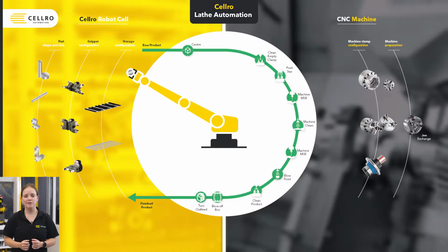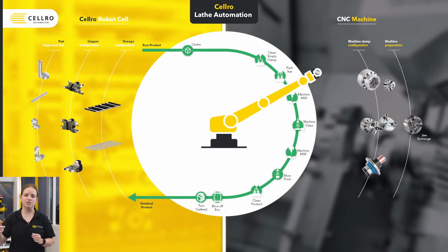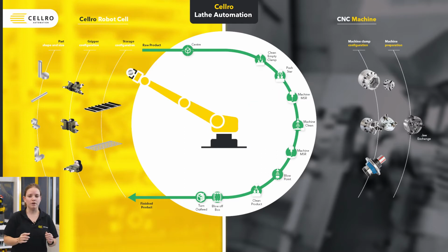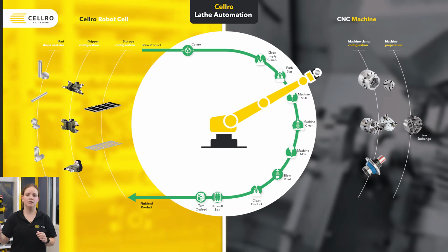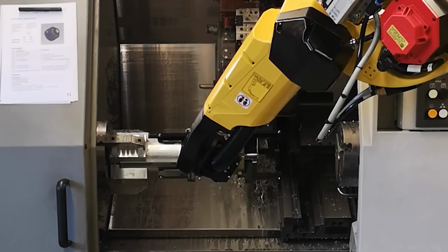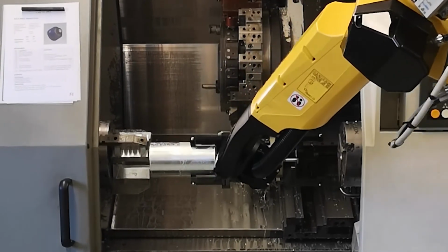The simplest one is to place a raw part in the machine and take it out again. This means that the robot will take a part from the tray and put it into the machine, start the machine, and when the machine is processing, take a second raw part from the tray, and after processing, exchange the two parts and put the processed part back into the tray.